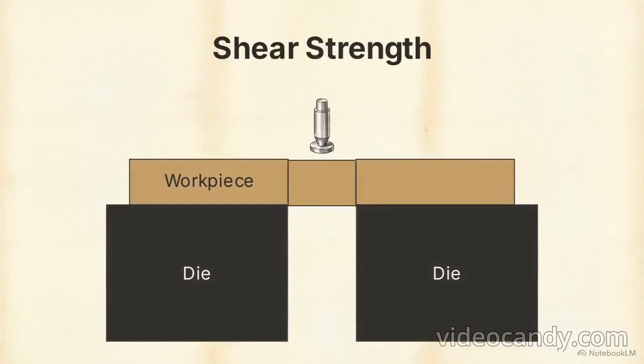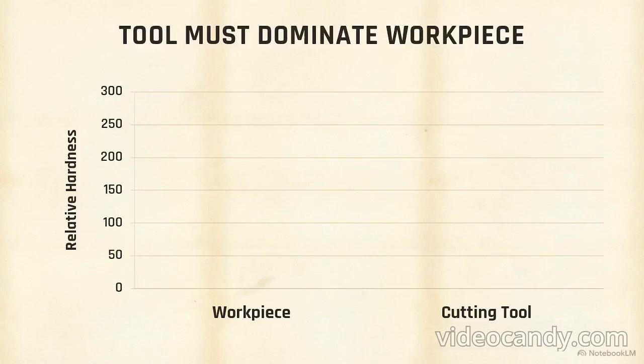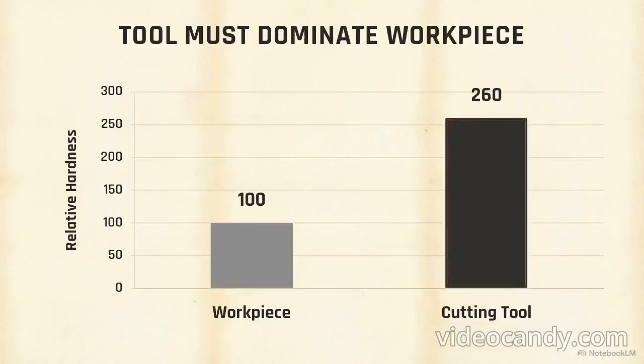This is the maximum load a material withstands before a sliding failure occurs along a specific cross-section. This force is applied during punching operations, where a press tool drives a die through a workpiece to shear out a specific shape. Engineers must also account for elasticity, the property that allows a material to recover its original size and shape after a deforming force is removed. These mechanical properties dictate tooling choices.